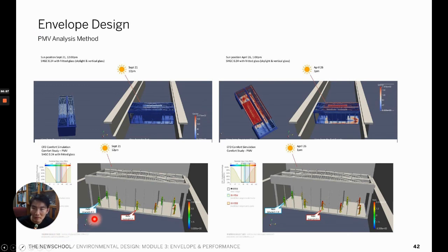And if you are worried about the space being overheated and some portion of the space being disproportionately hot or cold, you can directly take a look at how the people are feeling comfort based on controlling the input that we discussed, such as the closing value. So you can directly determine whether people at a certain location are experiencing discomfort at a certain time, and you can modify your design based on the simulation result.